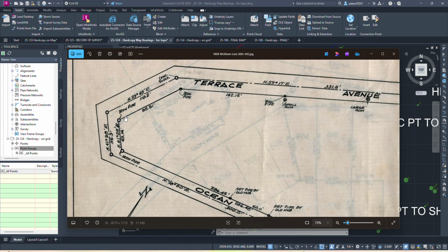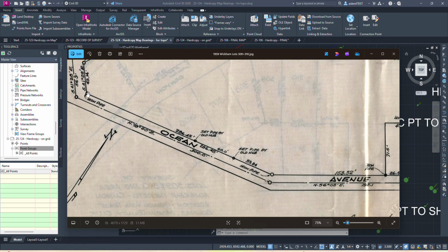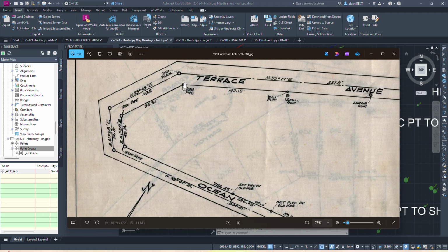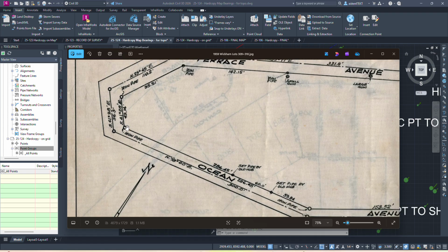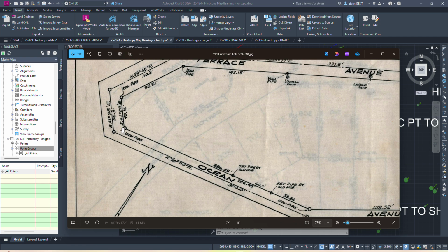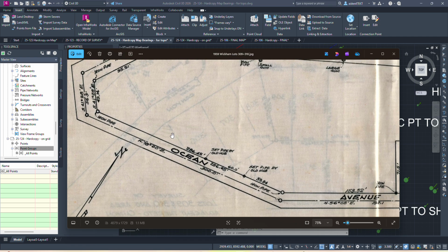If I hold these and I don't find this pipe, I'm just going to hold bearing and distance, record bearing and distance here, hold record here, and then if I found this one, just go to this one here, and I may change this bearing, right? I may just calc, hold this interior angle, calc it, hold this interior. I may change this interior angle to go hold here and then go straight to this found pipe, or whatever method I choose based on the best available evidence.